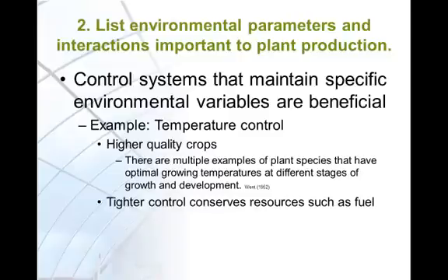A grower may ensure that optimal temperature is satisfied at all times by setting the thermostat several degrees above optimal. This choice ensures that temperature does not drop below optimum, but the temperature may at times be many degrees above set point. In this scenario, in the winter, overheating exacerbates heat loss through the greenhouse structure.